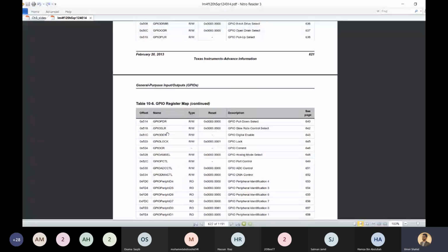Each and every register will have its own base address and its own offset value. So we will get a base address for any port. You will add some offset to that base address and you will access that particular register. And after accessing that register, you may either write to it or read the value from it. This is the same as assembly notation, but we'll be using this notation in your C language just for the sake of simplicity.